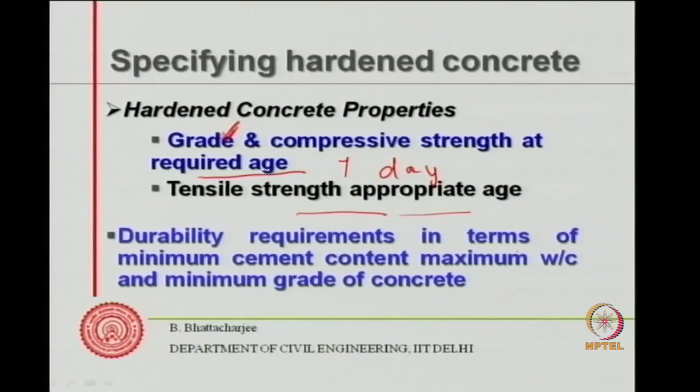All right. So durability requirements are specified in terms of some prescription of minimum cement content, maximum water cement ratio, and minimum grade of concrete, etc. All right.